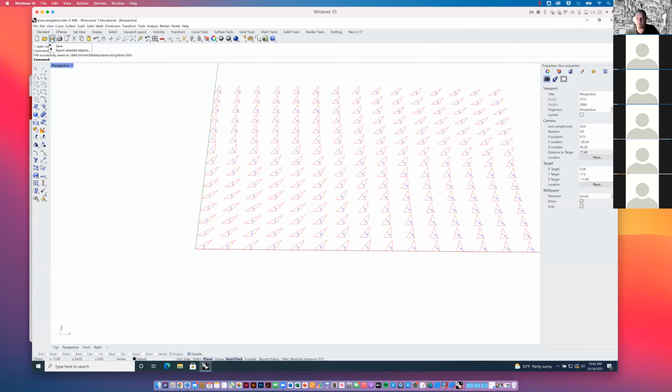All right, so bake that in, bake the labels. I changed the property of the text by selecting all the text at once, going to text properties, right? Cell text, text properties. Those are the two commands I used. Change the scale, the size, the font. Then I hit OK. I selected all the text again, exploded them into curves, and then joined them so that any curves that could be joined together into closed or joined shapes were.